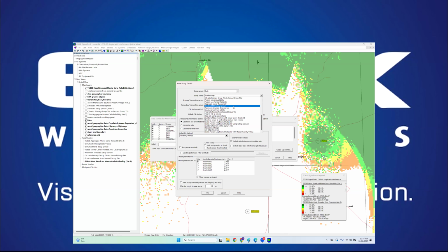In the latest revisions of the TSB 88 document, they recommend calculating the delay spread not based on just the direct difference in path length, which that's what these do, is we just take the path length, direct transit distance between them to come up with our delay times.